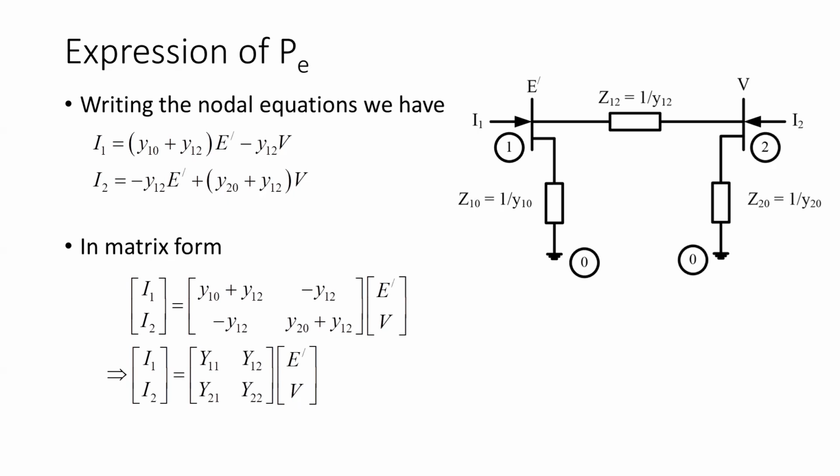You learned something, right? That you can eliminate one source, calculate for the other one, then again eliminate the first one. Remember that, right? There is a specific name for this: the superposition principle. Very good. Superposition theorem. That is the first thing. First of all, we apply the superposition principle. Then after applying it, we apply the KCL. So let me break it down a little bit because I'm not sure whether all of you are understanding or not. Initially we forget about I2.